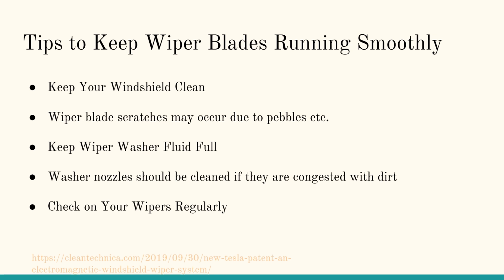Another one is to keep the wiper fluid full, which is used in washing the windshield. To keep the wipers functioning properly, ensure the wiper liquid is full. In case your wiper fluid spray does not cover the windshield entirely, examine the spray nozzles and clean them if they are clogged with dirt. Adjust the nozzles from time to time. Check on your wipers regularly.